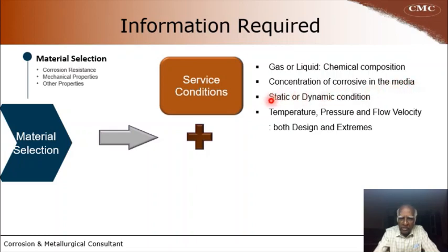Then we should know whether it is static or dynamic condition. Static means storage vessels. Dynamic means either pump or liquid flowing in pipe. Then temperature, pressure and flow velocity during design stage and also extremes are required because temperature, pressure and flow velocity affect the corrosion rates.